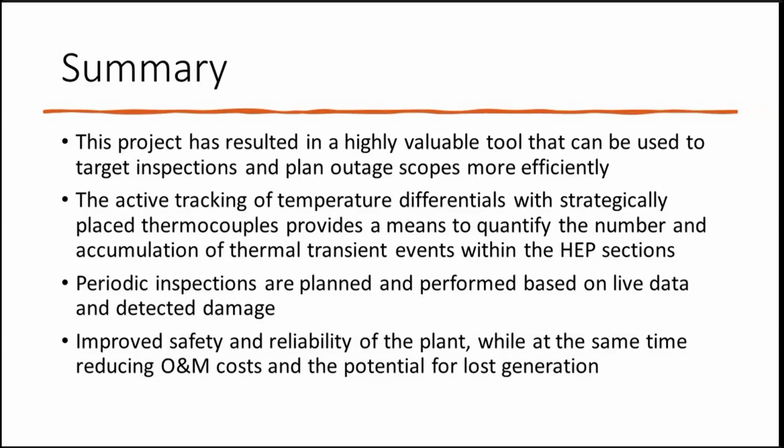Some of the differences or challenges in creep strength enhanced ferritic steels are going to be how accurate you want to get. A lot of what we're doing is somewhat Robinson's rule calculations using creep redistributed stresses and adjusting for operating data. But there's always room to sharpen the pencil. I don't think there's anything wrong with the material correlations for the CSEF materials.